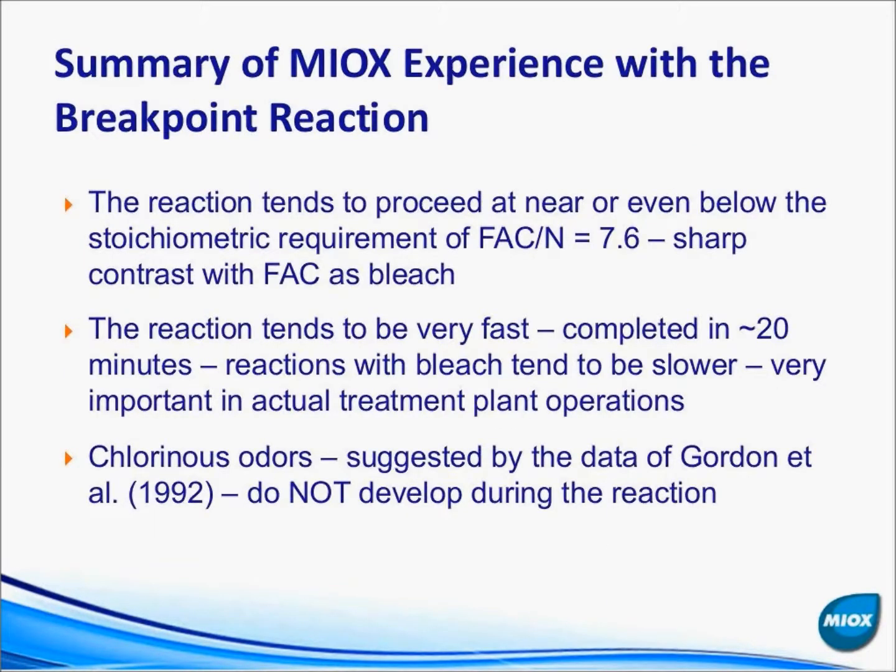So the summary of mixed oxidant breakpoint reaction, or MIOX experience with breakpoint reaction: the reaction tends to proceed at, near, or even in some cases a little below the stoichiometric requirement of free available chlorine to ammonia at 7.6. It's a very sharp contrast when compared with regular bleach. It's a much faster reaction. Reaction tends to be very fast as well, completed in approximately 20 minutes, whereas reactions with bleach have been demonstrated to be slower.